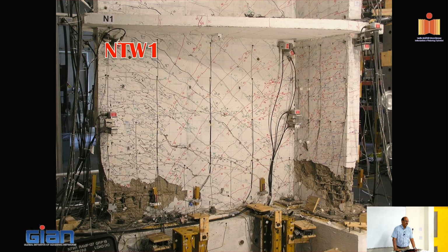So they do behave well, but the extent of damage associated with plastic hinging is pretty substantial. When you cause damage like that, your cover concrete goes off, and the longitudinal bars get exposed. In that case, they can buckle easily and fracture faster than if you can prevent that from happening.